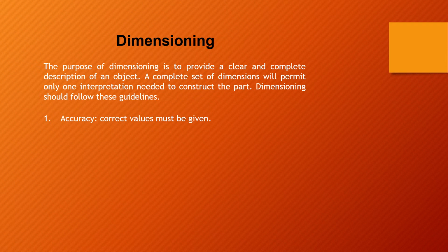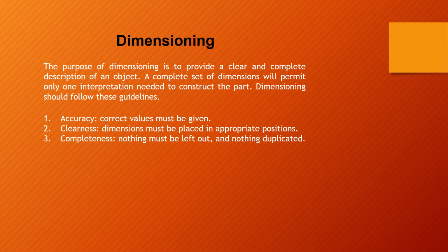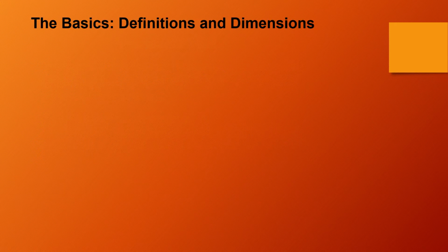Number 1. Accuracy. Correct values must be given. Number 2. Clearance. Dimensions must be placed in appropriate positions. Number 3. Completeness. Nothing must be left out and nothing duplicated. Number 4. Readability. The appropriate line quality must be used for legibility.